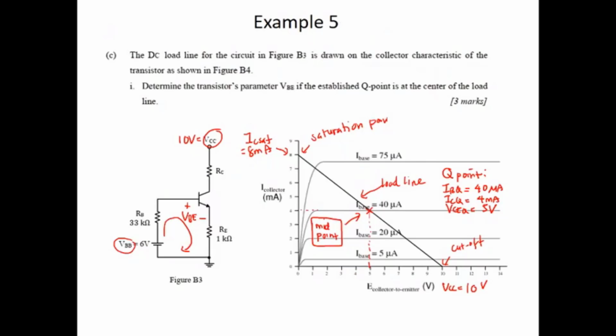The next question is we want to change the configuration. It is stated here that the emitter bias circuit shown requires 2 power supplies. See here we have 2 power supplies: VCC at the collector, and VBB at the base. Now, instead of 2 power supplies, we want to have a single power supply, so we will use the voltage divider circuit. The question is to draw the circuit and determine RB1 and RB2.